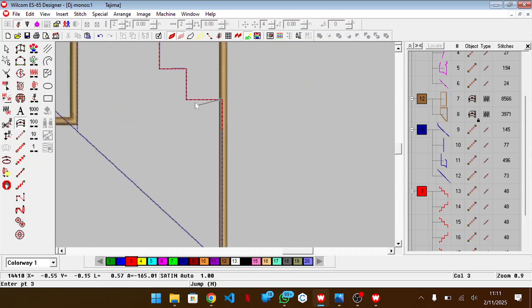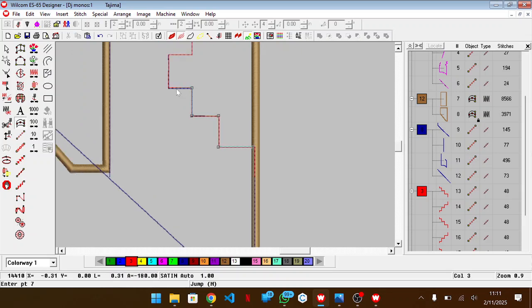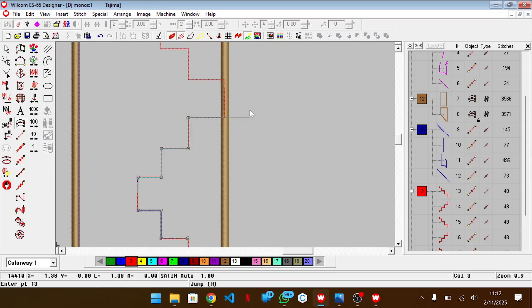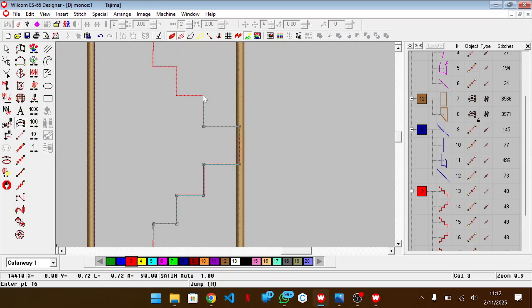So all those outline tools just help us trace accurately once and for all, once we are ready to use our final drawing tool, which is this input C line. I'm holding down control to get this straight line. Just control and go in the direction. So even if you see my cursor has strayed to another place a little bit, that control still keeps it well under control, so it will be straight like so.